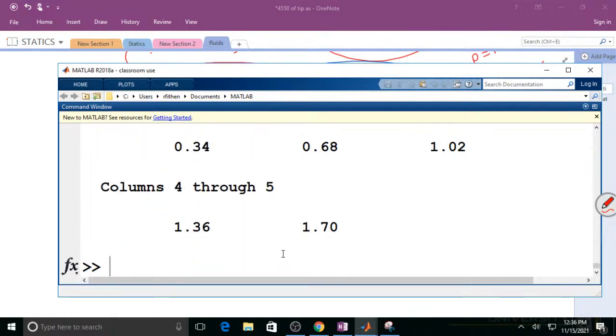There's my velocities. So what I'm going to do is I'm going to take the head loss equaling, I'm going to basically take 0.04 times 235 foot of pipe divided by 1/12 the diameter times the V squared divided by 2 divided by 32.2.